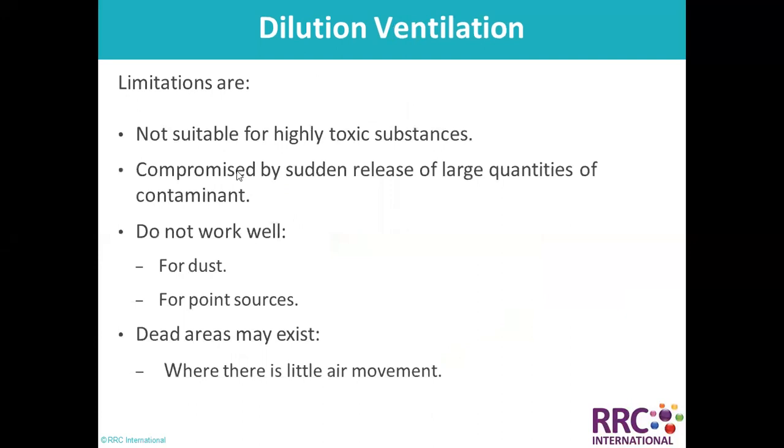But yes, there are of course limitations also. It is not suitable for highly toxic substances. It is compromised by sudden release of large quantities of contaminants, and does not work well for dust or point sources. Dead areas may exist where there is little or no air movement.